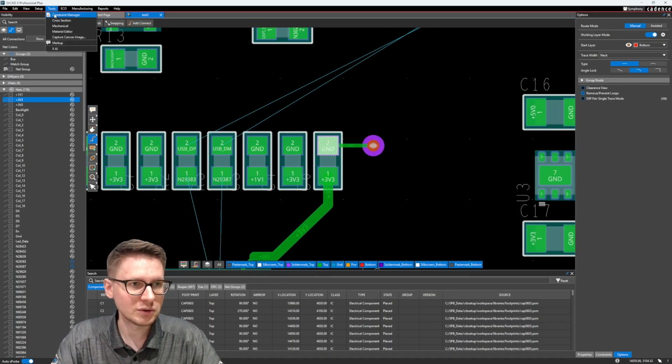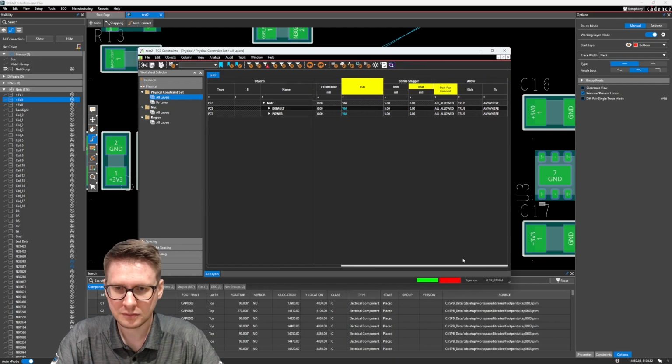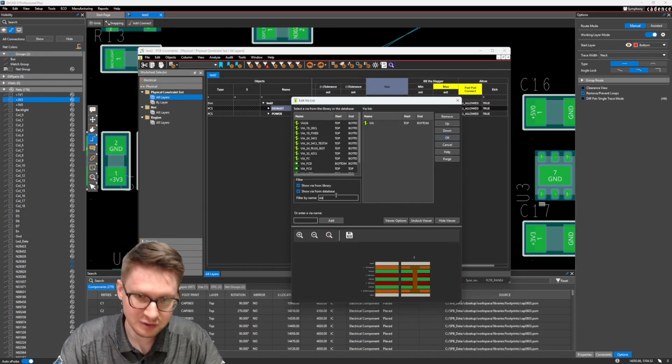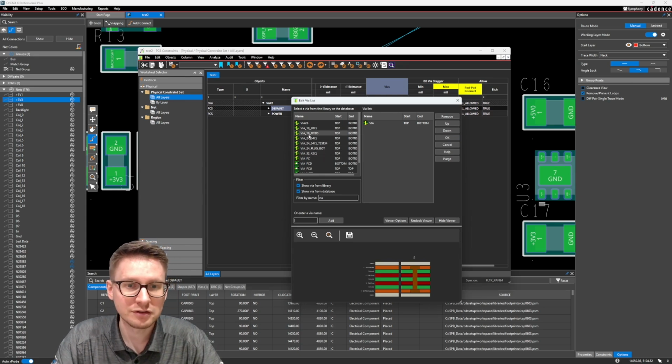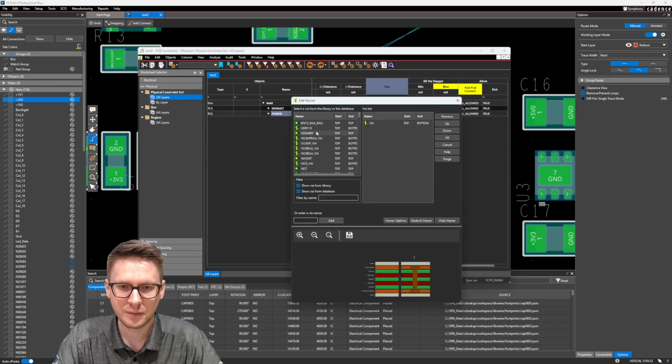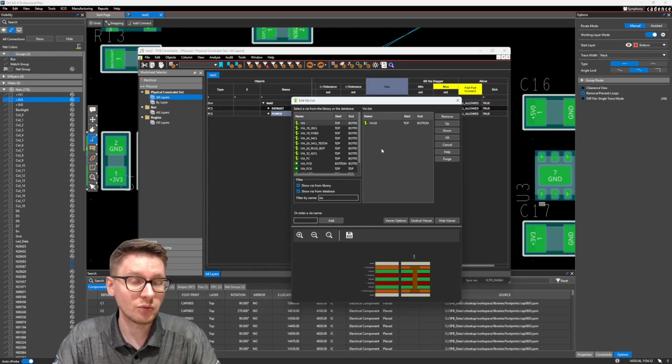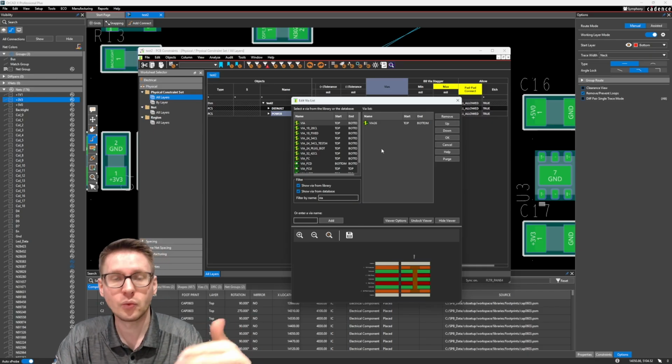What you can do is if you go to Constraint Manager, in this via section, double click, you can then select a different via. So if I type in via here, I know that I have a couple different vias which I can use. I really like this via 26 pad stack, which I've created. So I'm going to set this for my default and also for my power and use that throughout my design. You can have multiple vias also selected for different constraints. And then when you're routing, you'll just have an option of which via do you want to use to go from this top layer to bottom layer.